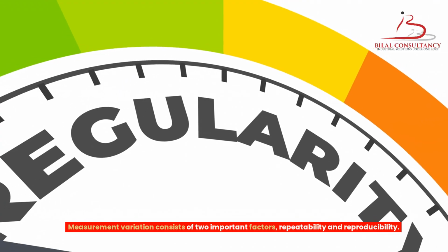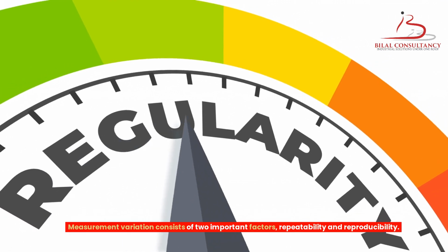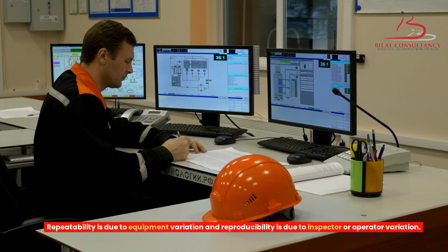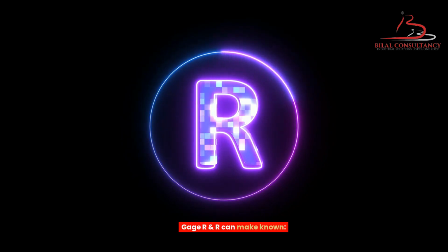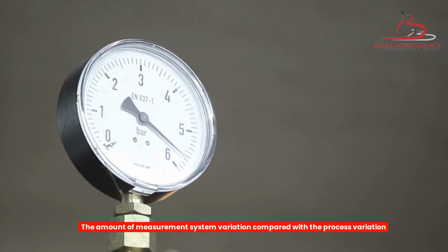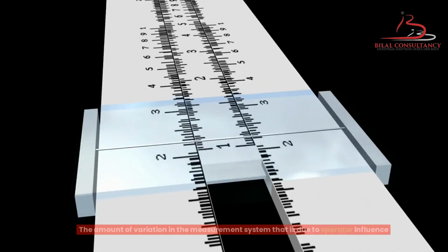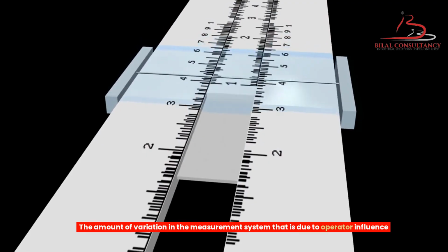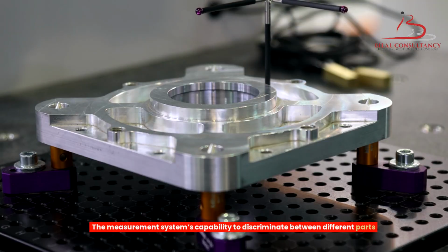Measurement variation consists of two important factors: repeatability and reproducibility. Repeatability is due to equipment variation and reproducibility is due to inspector or operator variation. GageRnR can make known the amount of measurement system variation compared with the process variation. The amount of variation in the measurement system that is due to operator influence. The measurement system's capability to discriminate between different parts.